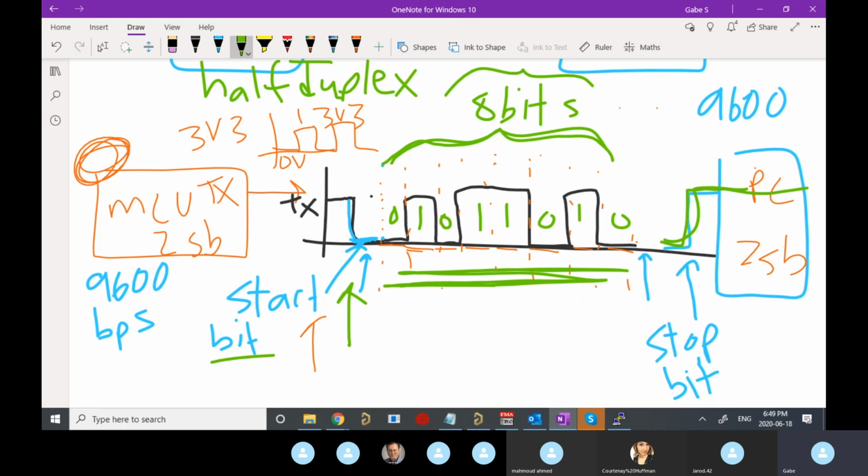Yeah, that's a great point. It's hard to keep a very consistent baud rate all the time. Like Mahmoud said, it's not going to be perfect. So yeah, that's a great point to bring up. It's really good for synchronization. And that's mostly because you don't share a clock, right? You're asynchronous, so you have to agree on a lot of things beforehand, and you have to make sure that everything is as synchronized as possible.